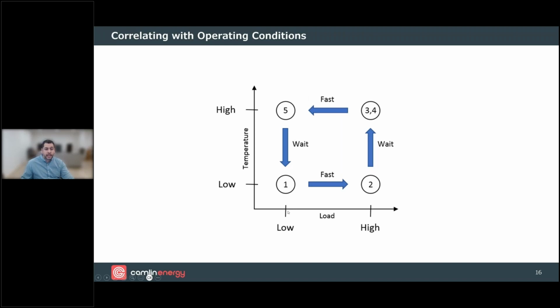In that guide, they prescribe doing the periodic partial discharge test at a range of different operating points: going from low load to high on machine startup, waiting for the machine to thermally stabilize, then reducing load. At each of these transition points, they ask for PD measurements to be performed.